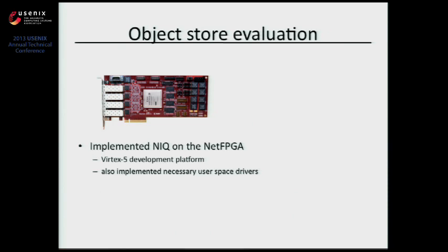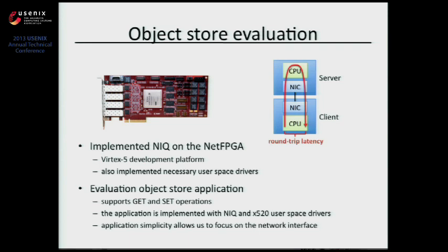All right, so we actually build this. We build this interface on an FPGA platform. We use the NetFPGA, which is a Xilinx Virtex 5 development platform. And of course, we went ahead and implemented all the necessary drivers in user space to evaluate our interface. And as a driving application for the evaluation, we used a very simple object store.